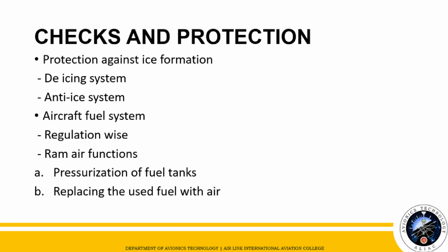The second system is the anti-ice system, which is the reverse paradigm, which tells us that if properly used, they prevent the formation of ice continuously, resulting in a clean wing with no aerodynamic penalties. An anti-icing system must have a means of continuously delivering energy or chemical flow to a surface in order to prevent the bonding of ice.